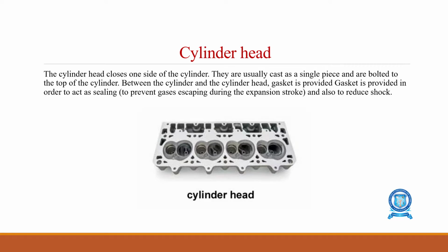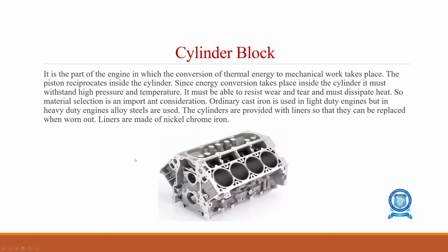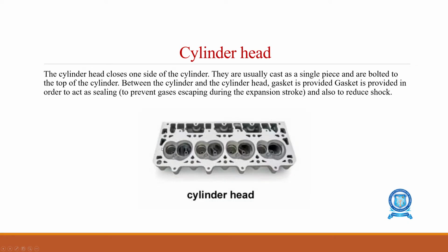In the cylinder head, that is the top cover, you can see above this the cylinder head will be placed. The cylinder head has the provision for the cam. The cam is a component which will be in the shape of an egg. Due to the rotation of the cam, the inlet and exhaust valves will get opened and closed.